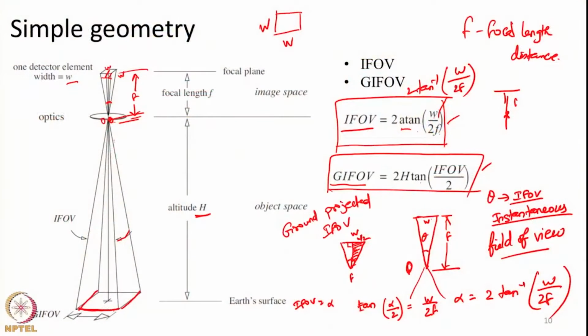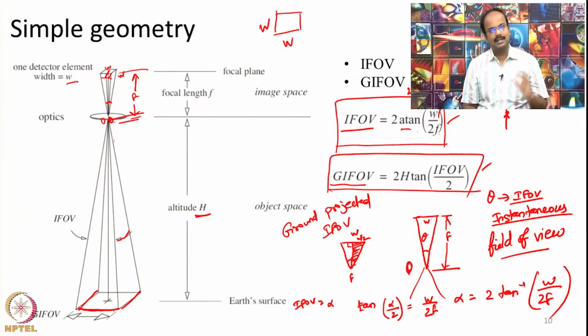That is the total scan angle of the scanner, or in the case of a push broom sensor, the total angle subtended by all the detectors in the cross track direction at the optical point where the light ray enters from the earth surface. Combined with the orbital height of the satellite, this gives the swath width of the satellite.